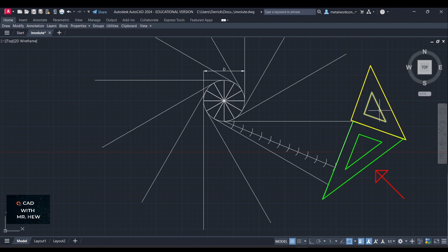Then you use your right hand to hold the yellow 45-degree set square steady on the table. Then you use your left hand to slide the 30-60 green set square in the direction of the arrow to each of these points, these arcs along this line.